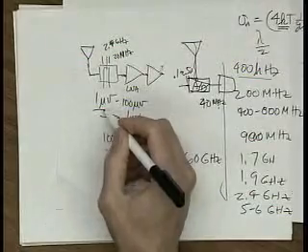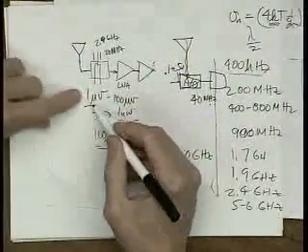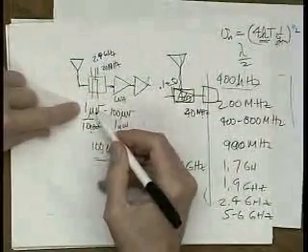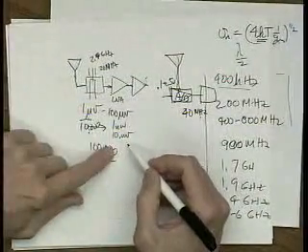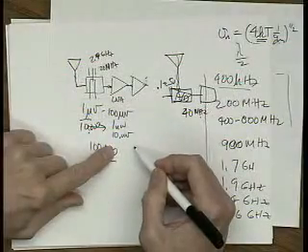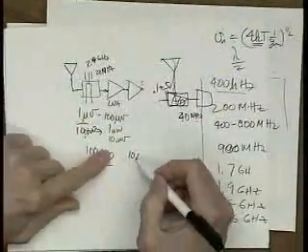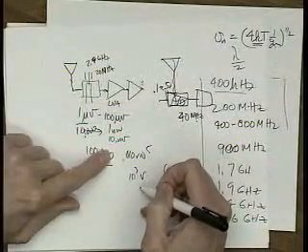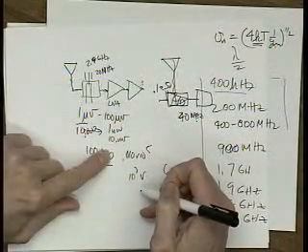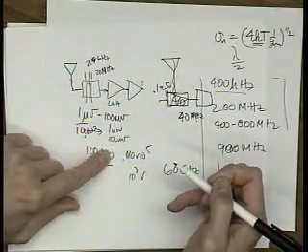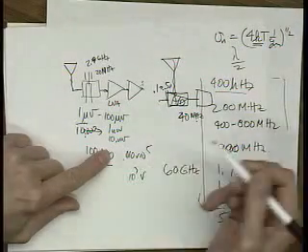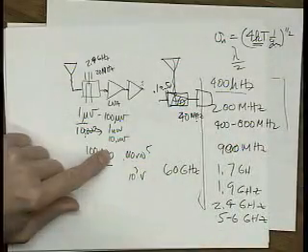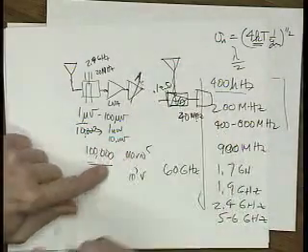If you have a gain of 100,000, that makes the 1 microvolt just fine. But in the 10 millivolt case, that's 0.01 times 10 to the 5th, which is 10 to the 3rd volts, 1,000 volts. Well, obviously, what happens before that? Some transistor goes out of saturation, right? It went out of saturation a long time ago. So you've got to have a lot of variable gain.